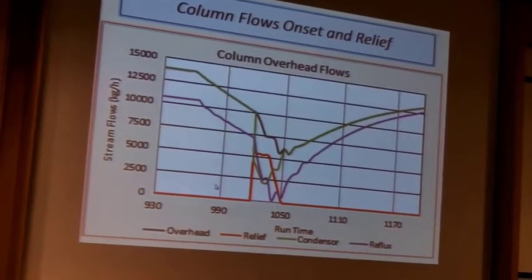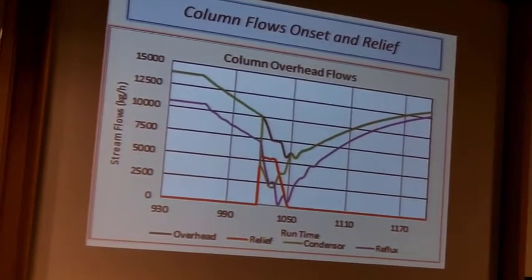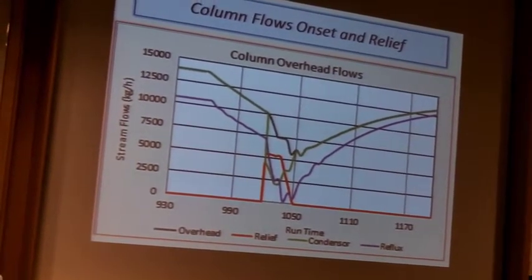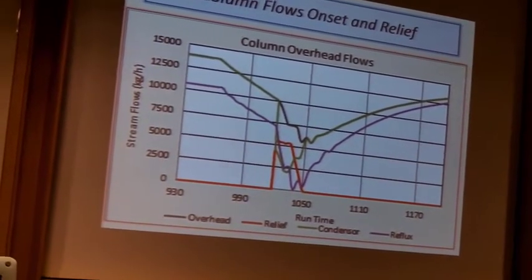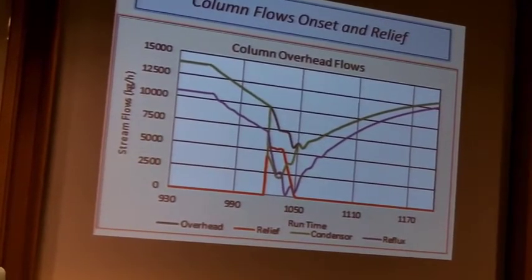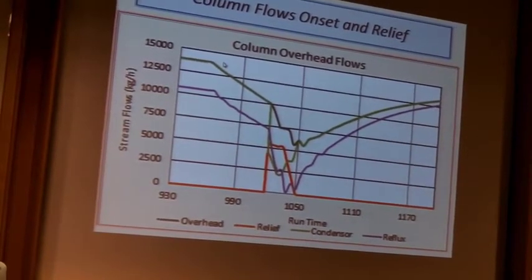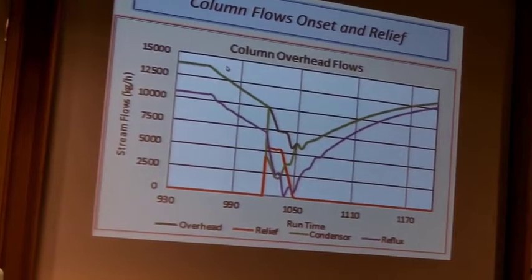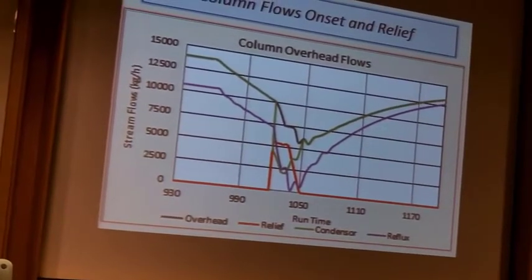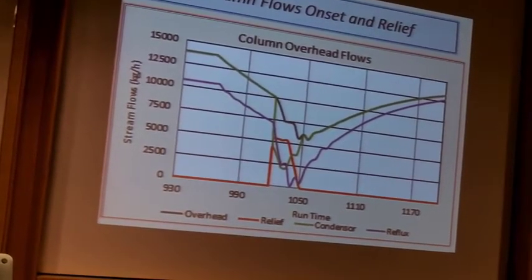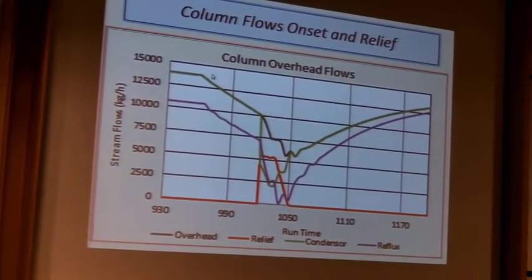And what this shows you, I mean, the traditional way of sizing relief valves on columns is to take the perceived maximum heat input to the reboiler based on its area and heat transfer coefficient. You take a latent heat, which could even be the feed latent heat, but wouldn't be very realistic. What you try and do is take the latent heat of the top tray at relief conditions, but I don't know how many people know what the composition of the top tray is at relief conditions. It's difficult to predict without a simulator. So basically you tend to oversize the relief valve with the conventional one.